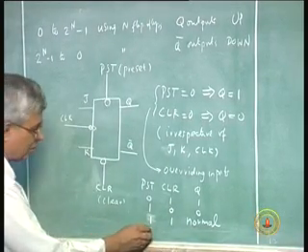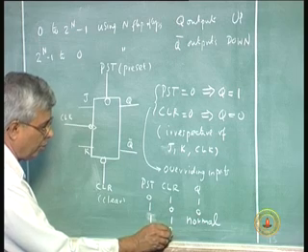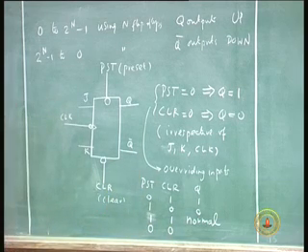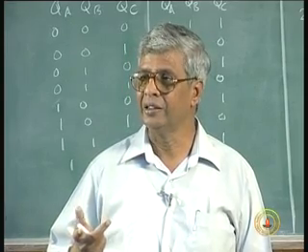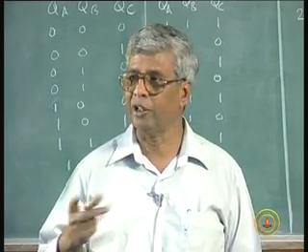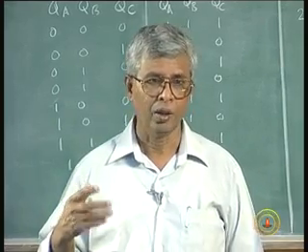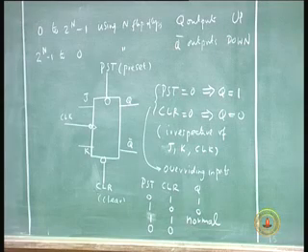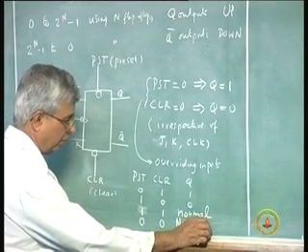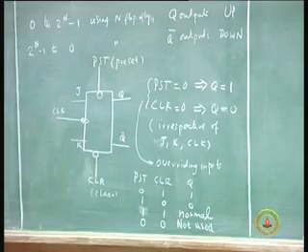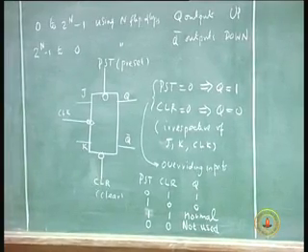And if both are 0, which is predominant, because each of them is an overriding input? When both are 0, which is overriding, we do not know that. So, this is one of those states which is not permitted. Do not try to make both clear and preset 0. That means there is an uncertainty there, and I always tell you the uncertainty should be avoided at all costs in any design. Make sure that preset and clear are not made 0 at the same time.